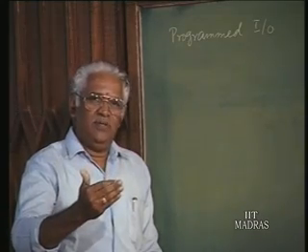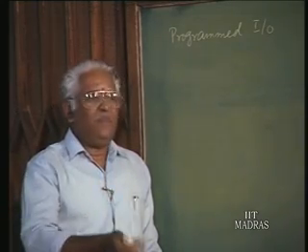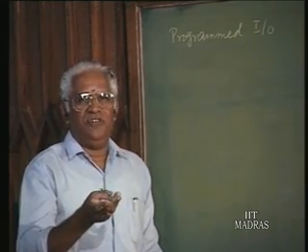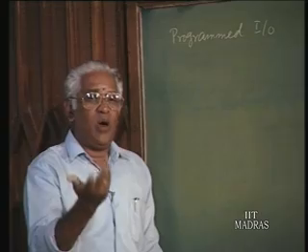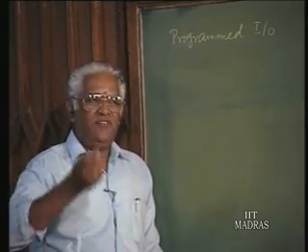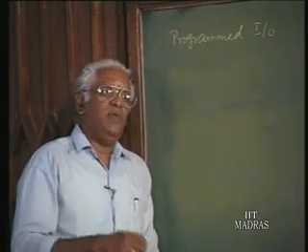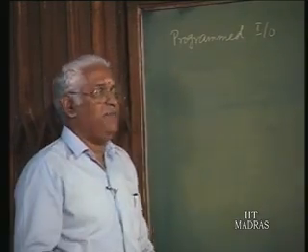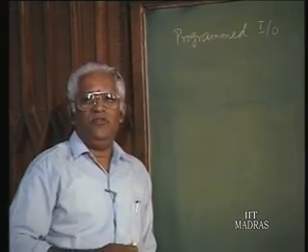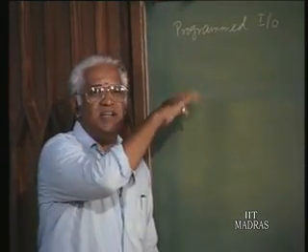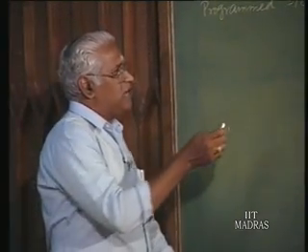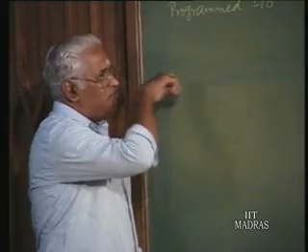device is ready. If it is ready, then it is going to move 1 byte and then keep track of it. Okay. So, essentially a counter will be used, a counter will be set to 5, let us say, and after the transfer of every byte the counter contents will be decremented. So that when the counter contents come to 0, we know that 5 bytes have been transferred. Now, those details I will just skip, I will not enter all those in the program. Okay. So, let us say